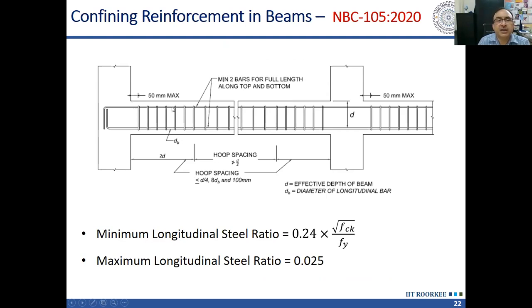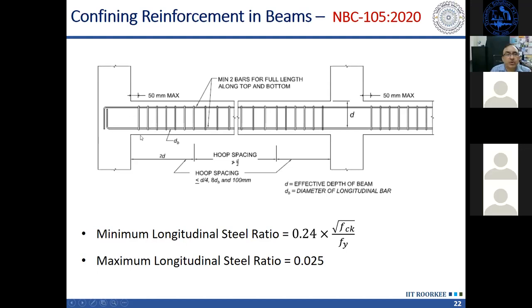So here the bending moment due to earthquake and dead load and live load gets added, whereas in the bottom reinforcement, when the reversal of earthquake occurs, we have the bending moment causing tension due to earthquake here. The gravity load will always cause tension at the top face. So the net moment at the bottom face will be much less as compared to the net moment which is causing tension at the top face. So usually the tension reinforcement at the top will be much more than that at the bottom.